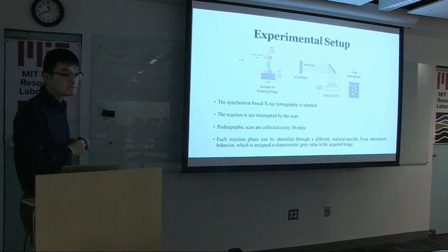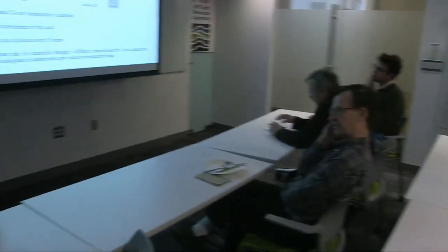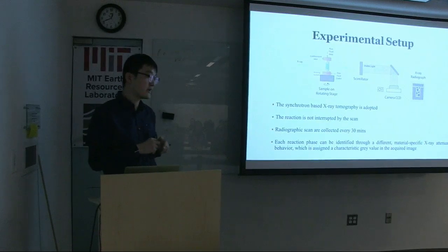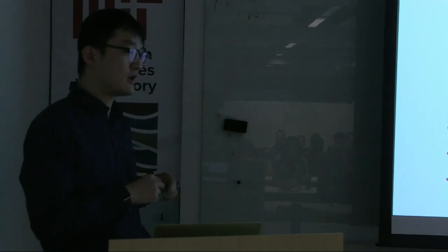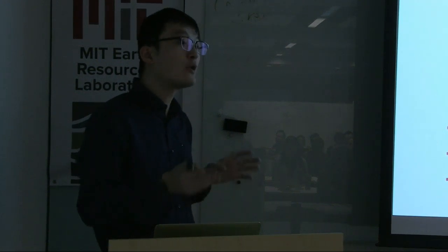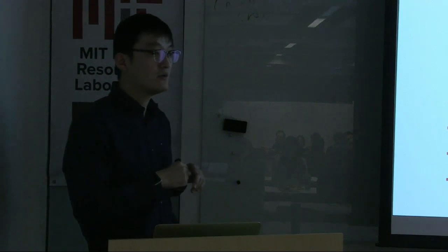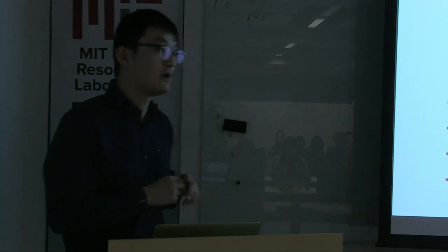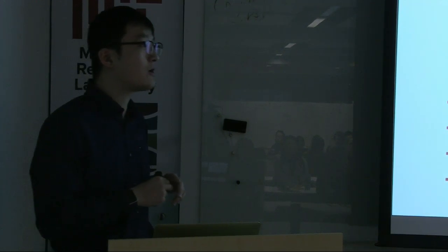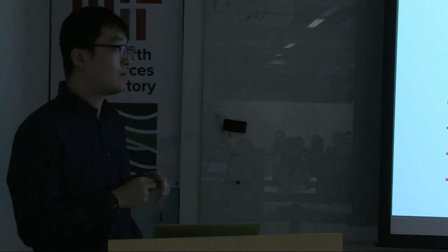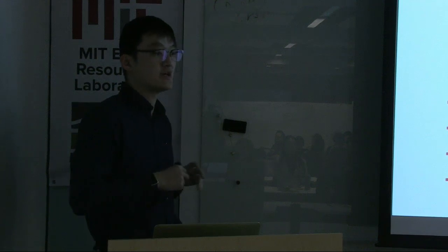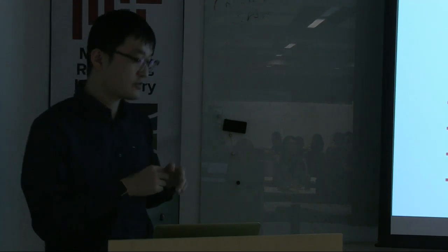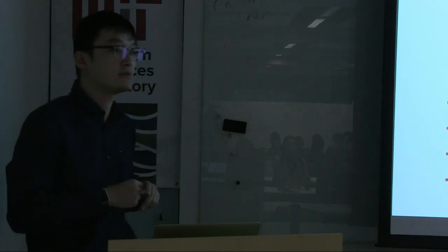So would your scheme be to dissolve the carbon dioxide into something first to inject it, or do you think it would actually be directly injectable? Well, for these industrial applications, I think there are ways. Basically, we pressurize the CO2 until it reaches what is called the supercritical state. Basically, it can flow like water, but still contain enough carbon dioxide. So I think that might be a good way to inject the CO2. And right now, there are tests run in Iceland, and what they do is use saline water and dissolve as much CO2 as you can in that solution and then inject it. And one thing about supercritical CO2 is that you have to have enough pressure to maintain that condition.